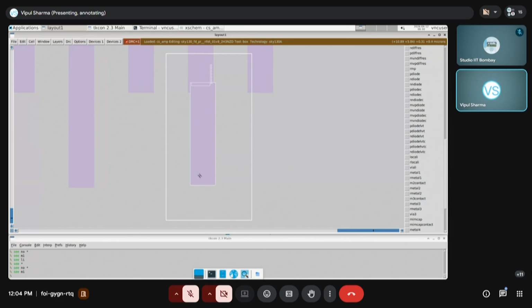So in order to rectify this error, I have to align this layer with the finger source terminal. So I will select this, bring the cursor, press the S key, and I have to move it with small steps. So rather than doing the M command, I will use key number 4 on my numpad. As you see, this layer moves to the right.